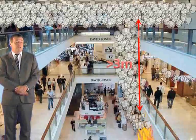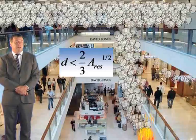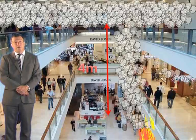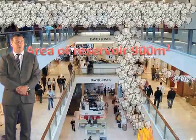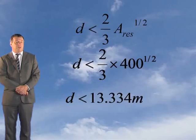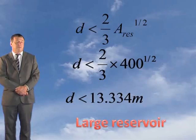Well, how large is large? A reservoir is considered large if the depth of smoke within it is less than 2/3 times the square root of the area of the reservoir, as shown in this simple formula. As an example, if the depth of the smoke is 4 metres and the area of the reservoir is 900 square metres, then applying this formula gives us the results shown here. And so the reservoir would be deemed to be large in this case. In practice, most reservoirs in shopping malls are deemed to be large.